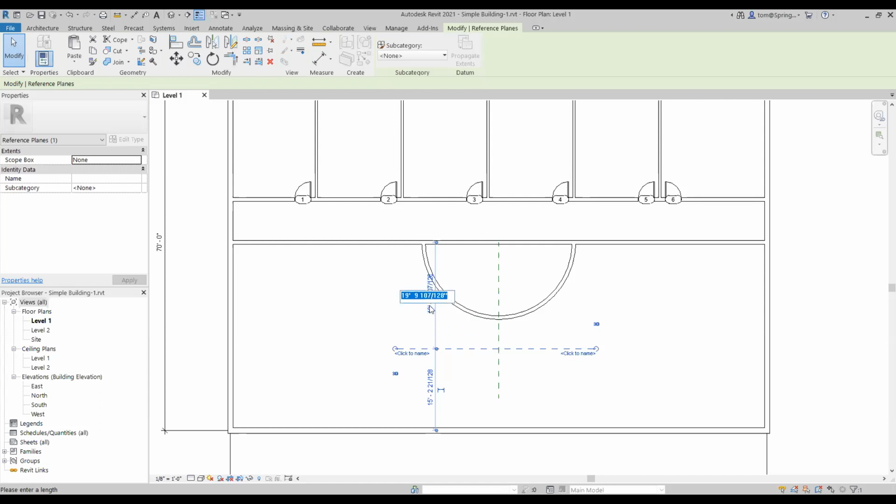So I'm going to click on that and change it to 20. Okay, so it's 20 feet. Hit my enter key, and boom, it goes ahead and moves a little bit. Yours will do the same thing. So you just want to make it like that, so it says 20 feet. You click on the temporary dimension, and this is how Revit really shines. You go ahead and place that.